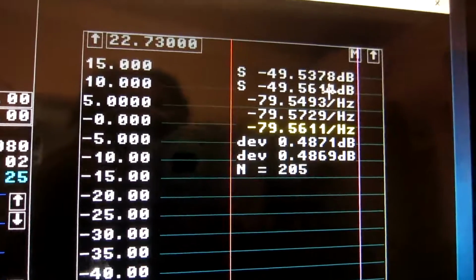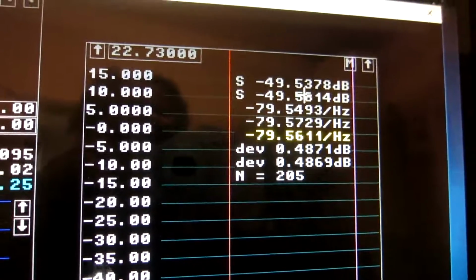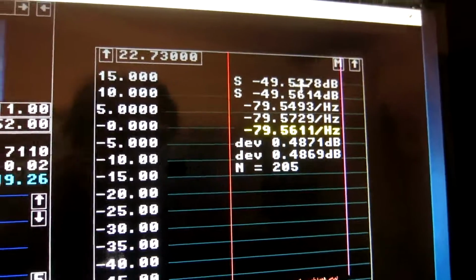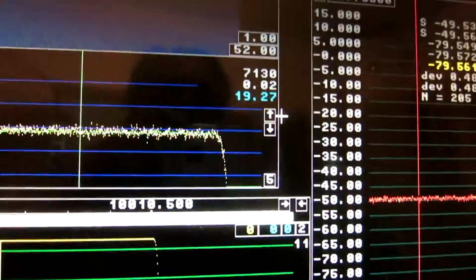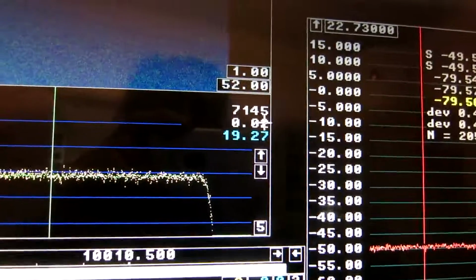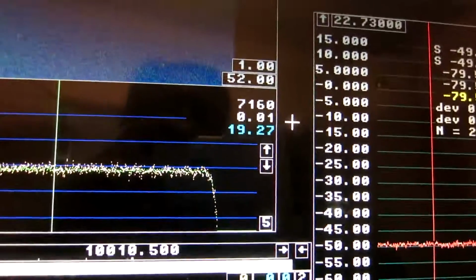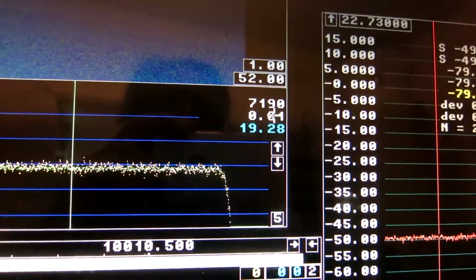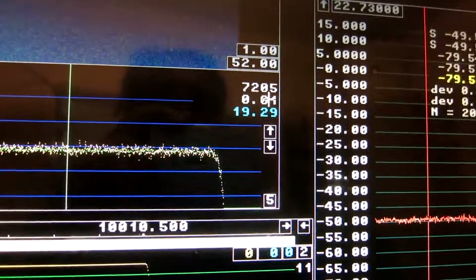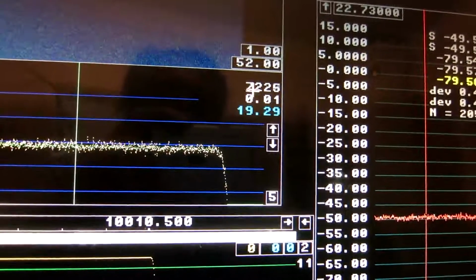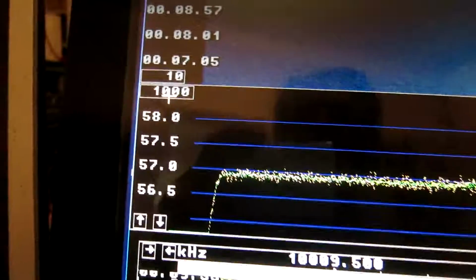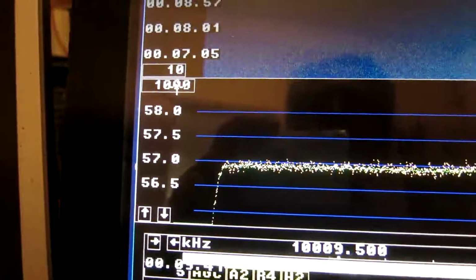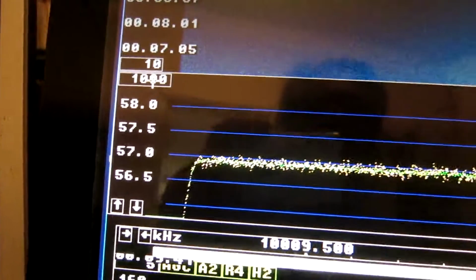There are, is it 0.3 decibels or something here that differ between the channels. That is part of the explanation for this not being exactly zero. And also the noise, because this is the difference between the correlation spectrum, which is very accurate, and 1000 averages of the power spectra.